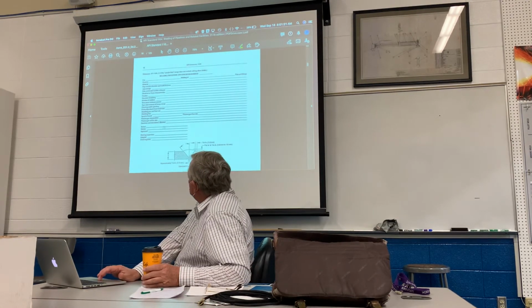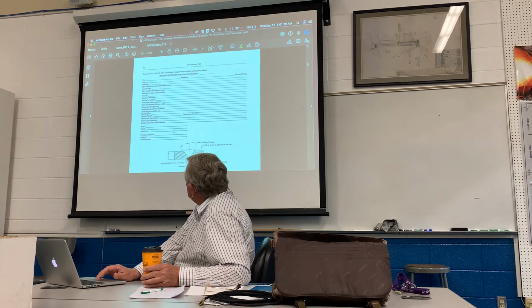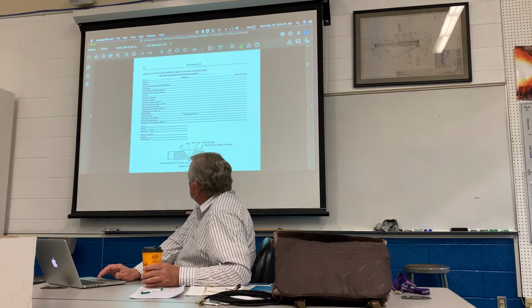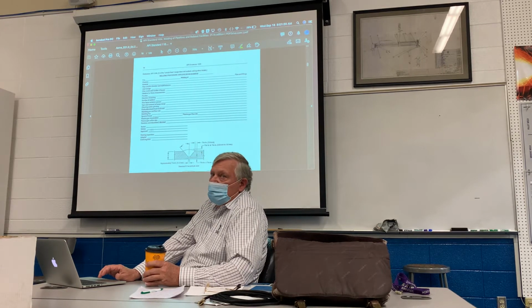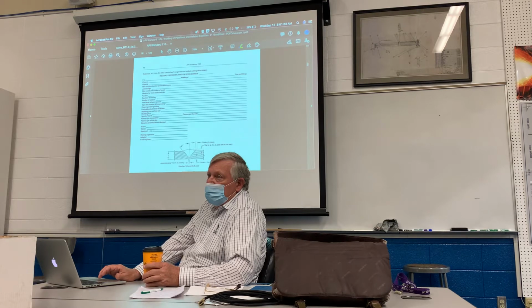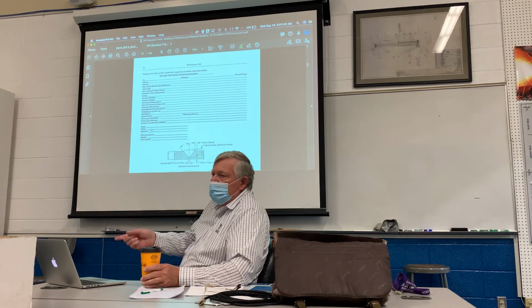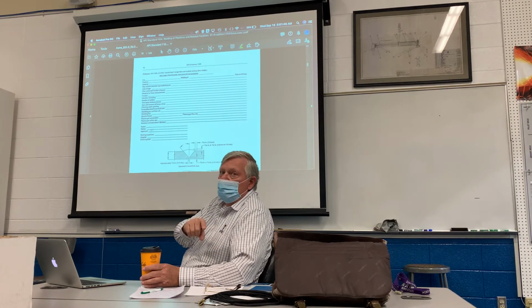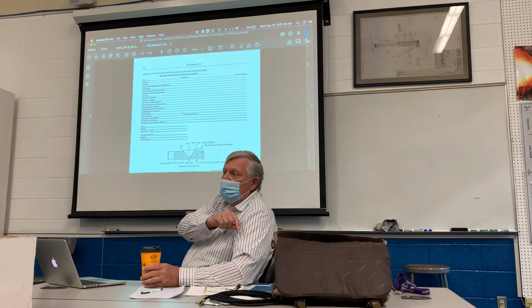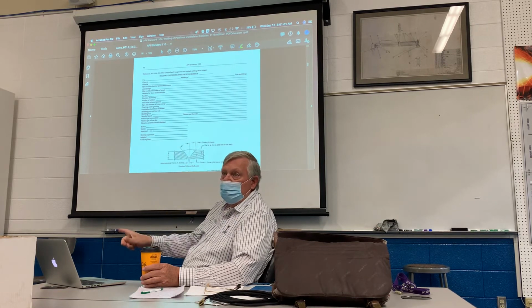That's why. Okay, so the welder's name and his 4-digit designation code, and then the approval is going to be done by whoever is doing the testing. So you would be the welding inspector in that case. What I want you to do when we're filling these out is fill these out and designate somebody else in this class to be your inspector that's going to look at your WPS and sign off on it.